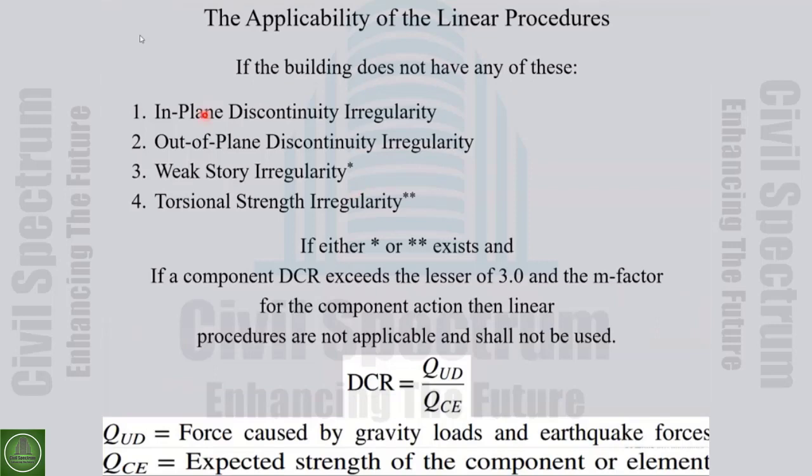We mentioned the limitations for linear procedures, when we can apply linear procedures. In a very general sense, I said when the strength is regular, we can use linear. But if the building is very irregular in strength, then it is better to use non-linear. But the more detailed articles are like this.